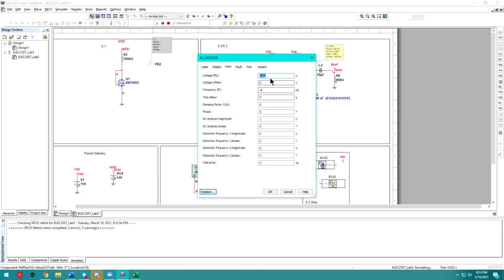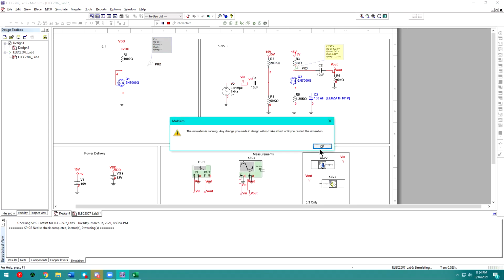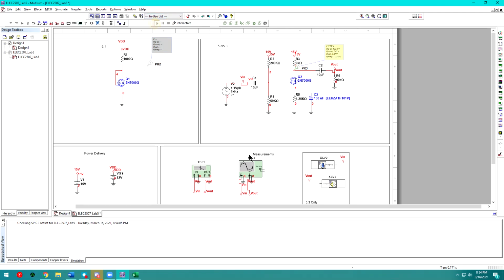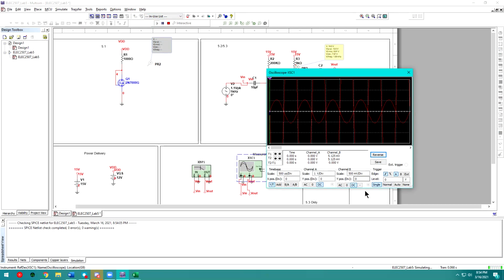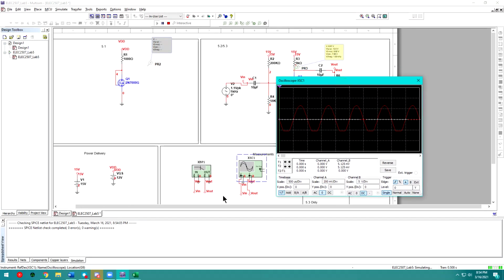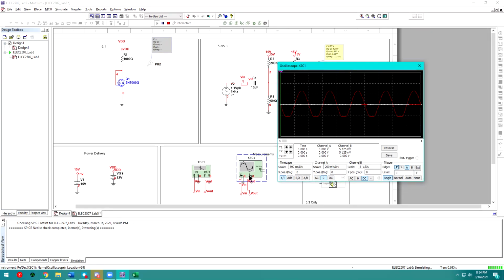Go ahead, hit run. Let's try 1.1 volts to begin. Make sure your oscilloscope is also connected. You're going to have to lower the channel B down. You might want to zero channel A. That's fine, we're not really worried about the input voltage, so zeroing channel A is fine. Channel B, we can see, is clipping at 1.1 volts of input. It's clipping on the bottom because we have these non-apparent peaks.